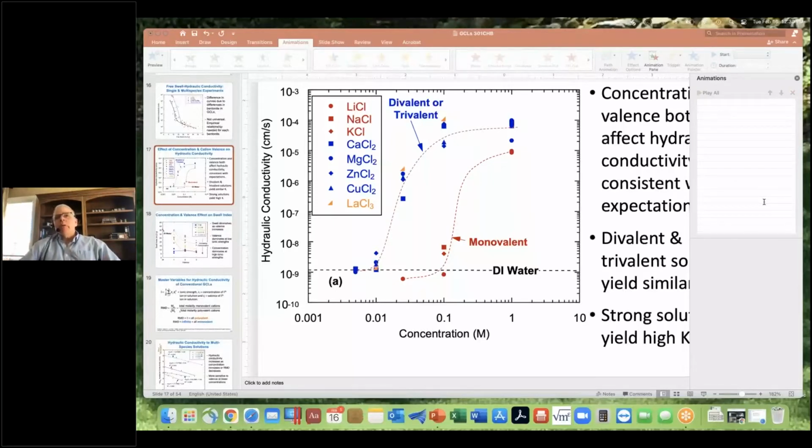The final gravimetric water content, or weight of water over weight of solid, is going to depend on the stress condition as well. So you have to be a little careful using that as an equilibrium criterion. I don't normally report that, except for the final water content. Typically, trying to think of numbers that we see, at the end of a test, 120, 130 for a chemical solution.